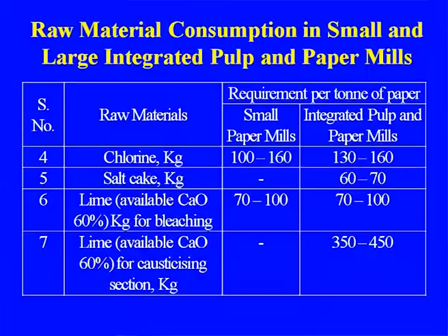Other raw materials are also used, because now the requirement for bleached paper, meaning white paper, has increased, so for bleaching it may be chlorine. Earlier it was chlorine, now it is chlorine dioxide, but as we are talking about chlorine-free bleaching, and in some mills the oxygen requirement, we will have to produce oxygen.